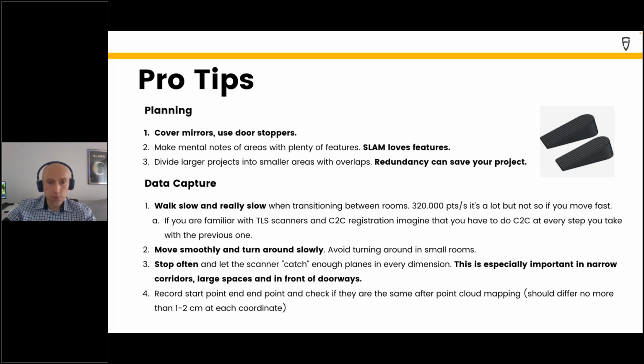Very important. Point the scanner to areas with plenty of features. As Dennis said, that demands planning of the scanning path. The planning is crucial. Do not rush.